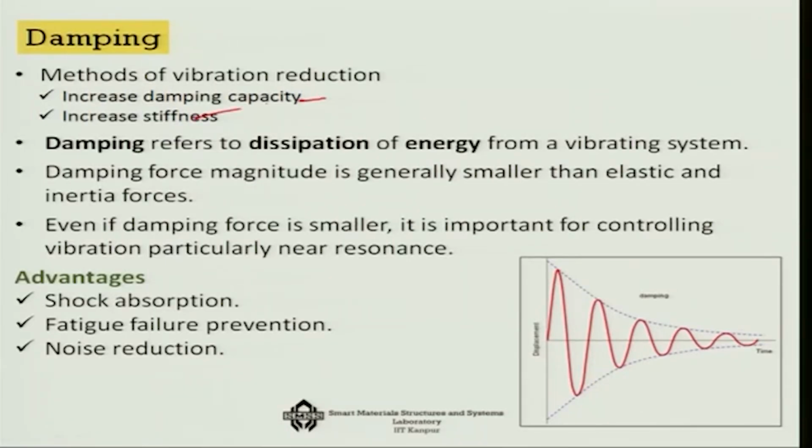Damping specifically refers to the dissipation of energy from a vibrating system. So, it is mostly the damping that is important, particularly during the resonance of a system. That means, when the natural frequency matches the excitation frequency, it is the damping which plays the predominant role. So, the damping study is very important and that helps in terms of shock absorption, fatigue failure prevention, noise reduction,